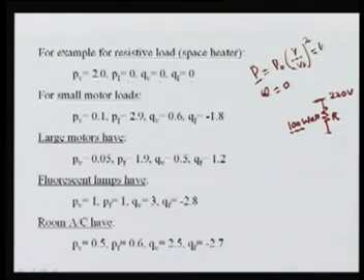It will be 100 times V divided by 220, sorry, and then squared. So if your terminal voltage is 220, then it will be unity and it will again be 100 watt. But if voltage is reduced to, let's suppose, 200, then it is 200 divided by 220, squared, so your output will be reduced.